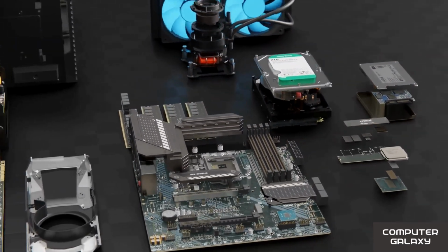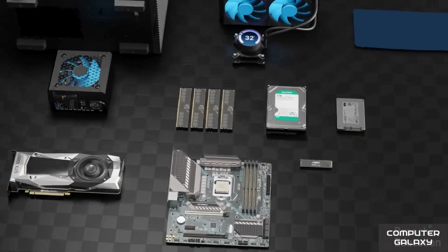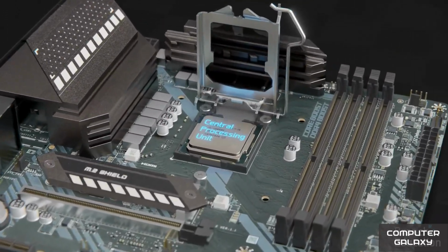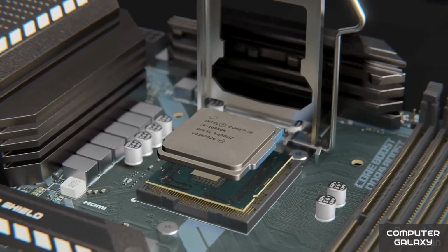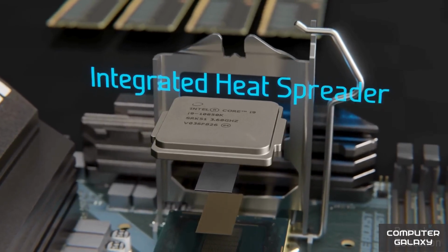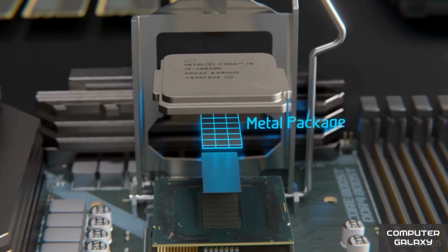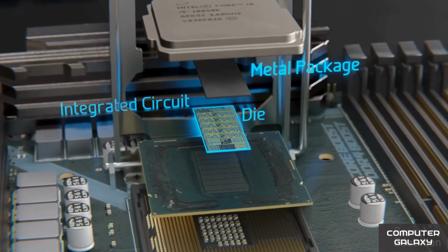As a result, here's all the hardware that we'll explore throughout this video journey, starting with the Central Processing Unit, or CPU, which is the brain of the computer. On top, we have the cover, called an integrated heat spreader, and inside is a smaller metal package that holds the integrated circuit, which is technically called a die.